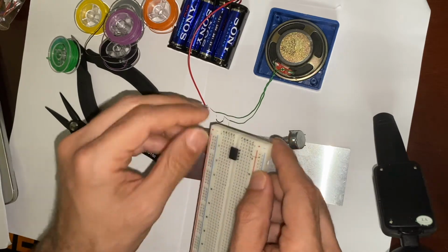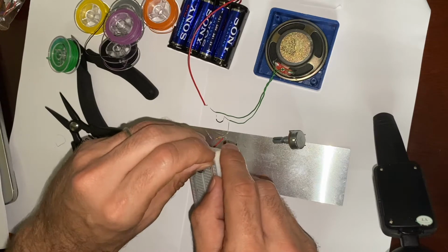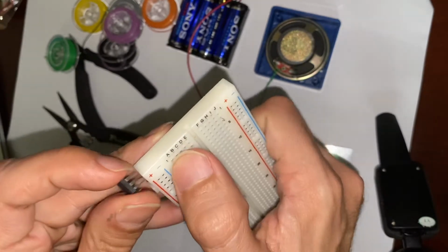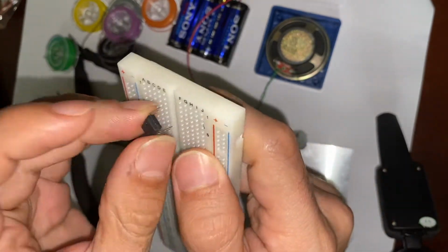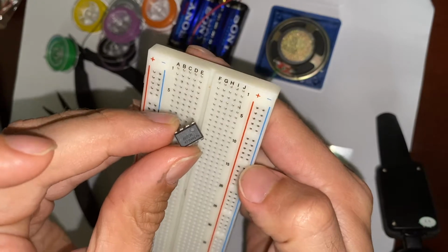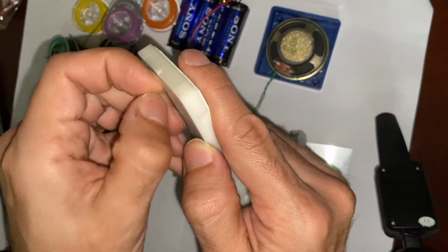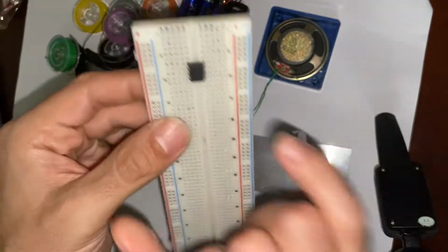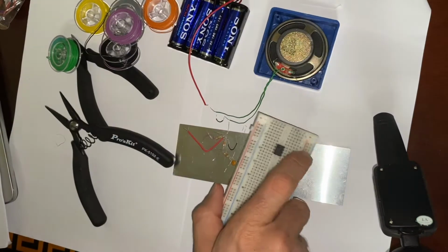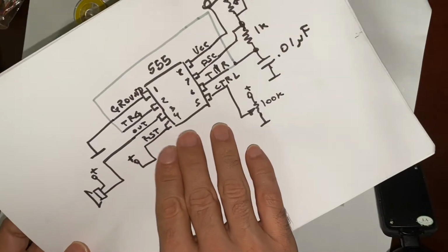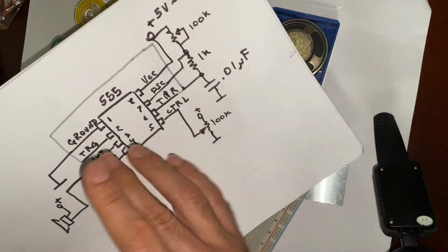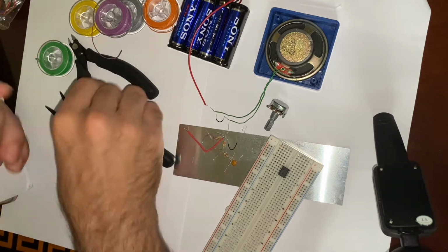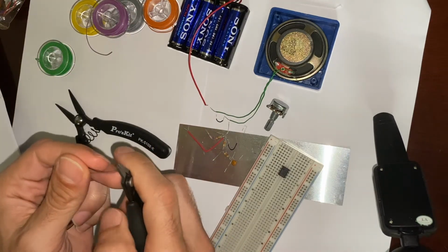Let's start by saying, okay, there is a breadboard, and we have to read how to use it. We have to be aware of what to connect where. So the mid slot is not connected. The A, B, C, D, E are all connected. F, G, H, I, J are connected, but in between the half of the left and the half of the right are not connected. So the dual-in-line package has the advantage that I can insert that in there, and you can relate how I put the connections and I center the chip similar to the diagram I made.